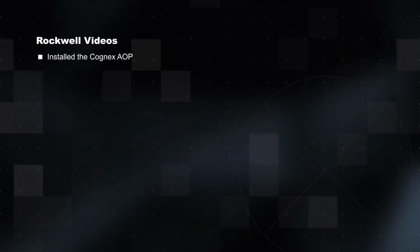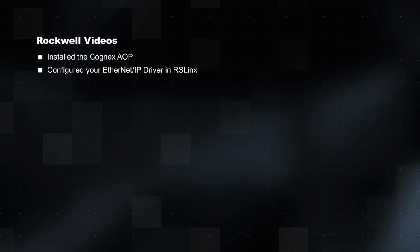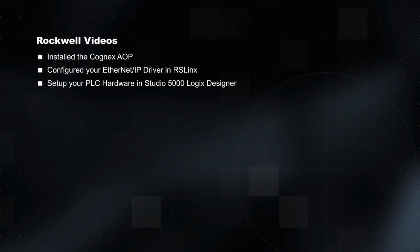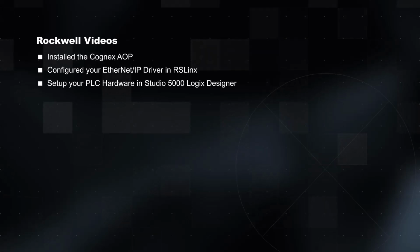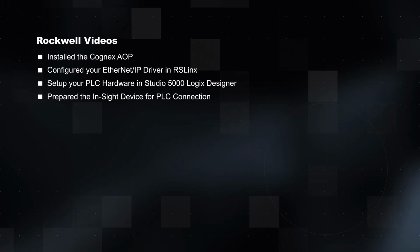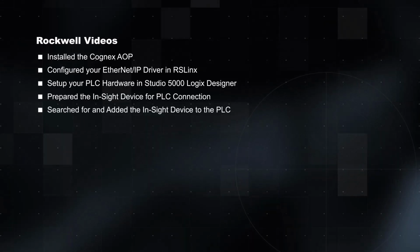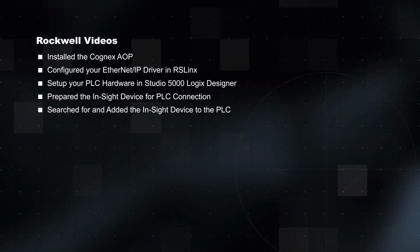This video requires that you have already installed the Cognex AOP, configured your Ethernet IP driver in RSLinx, set up your PLC hardware in Studio 5000 Logix Designer, prepared the Insight device for PLC connection, and finally, searched for and added the Insight device to the PLC. If you need assistance with any of these steps, please refer to their videos.